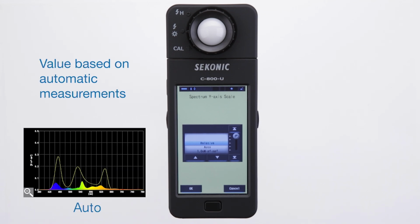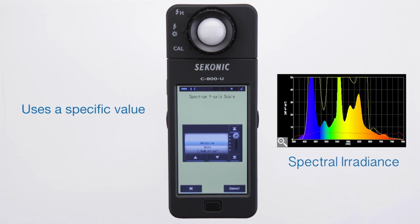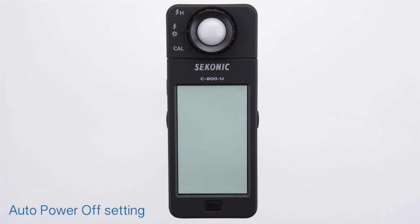Auto spectral distribution chooses the appropriate y-axis value based on the readings measured automatically and plots them on the spectrum graph. Spectral irradiance uses a specific value that can be selected from 1.0 to 100 micro multiplied by watts per square meter per nanometer. Next is auto power off.